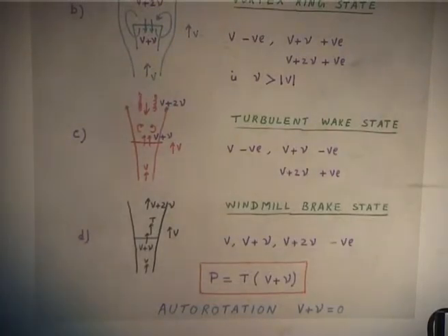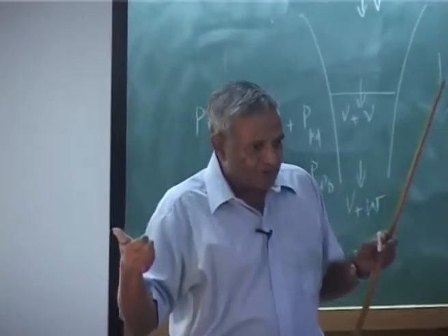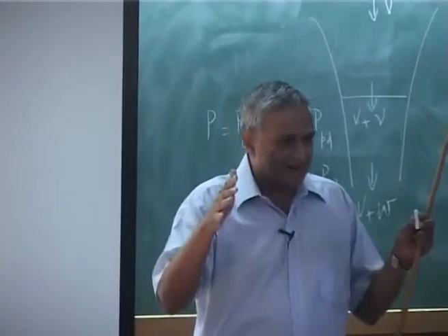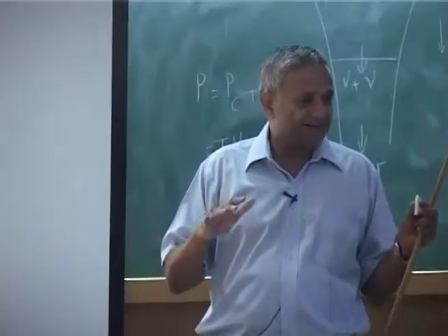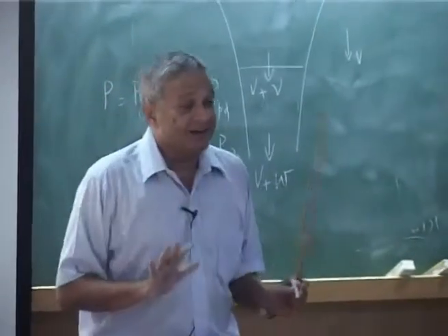Suppose you start descending faster than that condition, what you are doing is you are generating power. When you start generating, that means the rotor will start going faster. But for your blade, there is a limit in the design, you will have a centrifugal force which acts at a particular RPM. I told you right at the beginning, in helicopters your rotor omega is a constant.